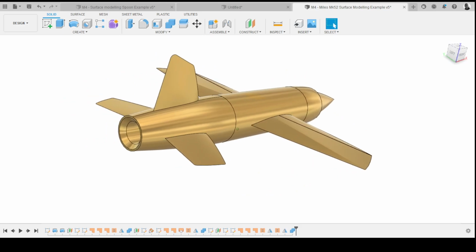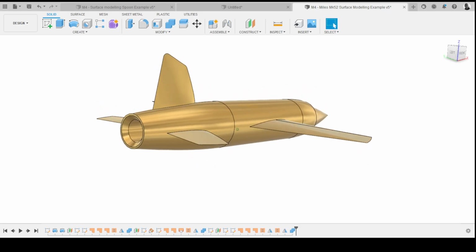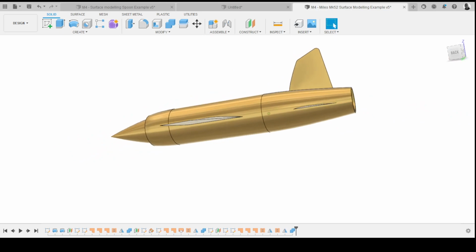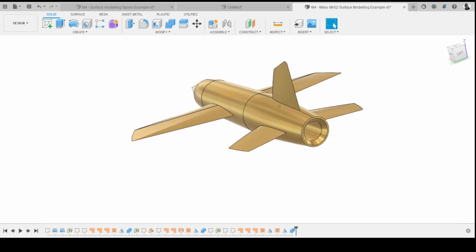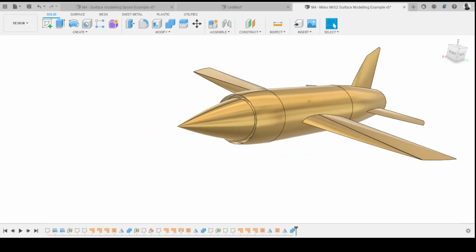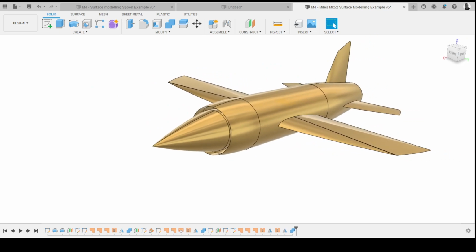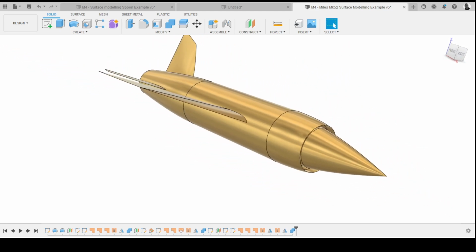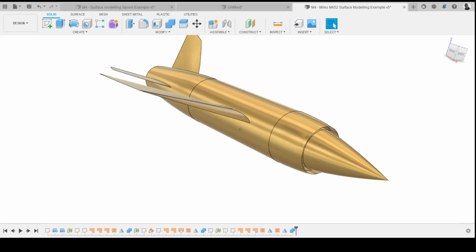And you can see there's a lot of surface modeling in the timeline. It's a solid model, but any ideas why surface modeling might have been useful here? If I spin around, any ideas? Wings. The wings, and why would it be useful to do that with surface modeling as opposed to solid modeling? The curves themselves. You could do the curves as a solid loft. I guess there's one particular thing about these wings. They came down to a very, very fine point, basically. They're almost razor sharp on that model.